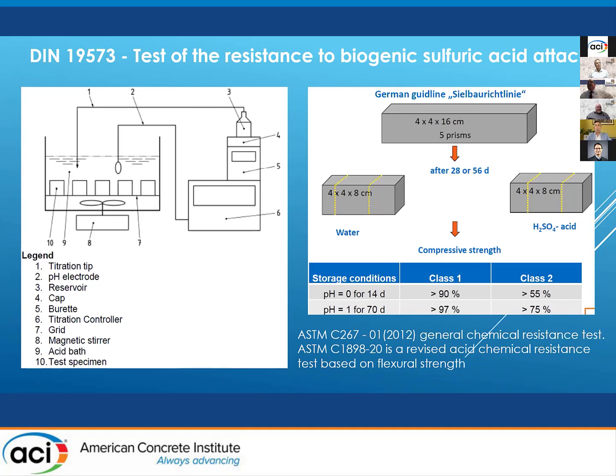The procedure is an immersion test relatively similar to the C267 type of test, but they did have guidelines for this. So one of the utilities was interested in using this test because it was a formalized international standard, and it actually gave performance parameters for different levels of resistance, exposure to pH of 0 and pH of 1 for 14 and 17 days respectively.